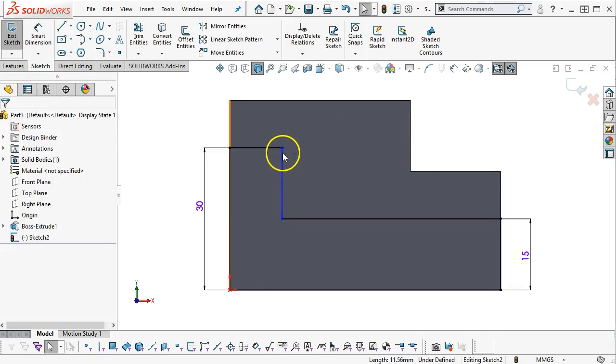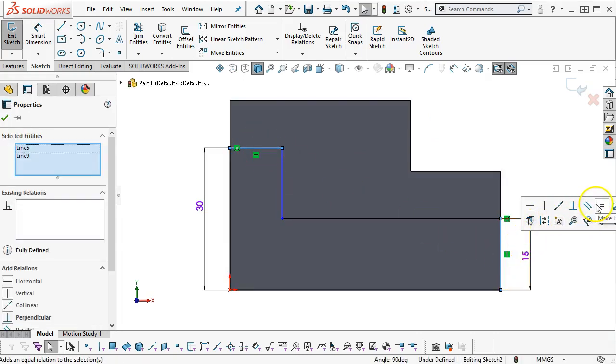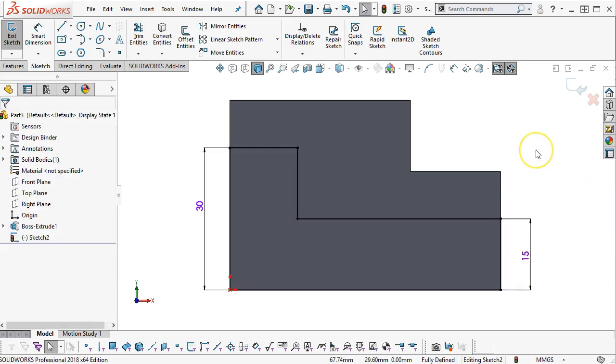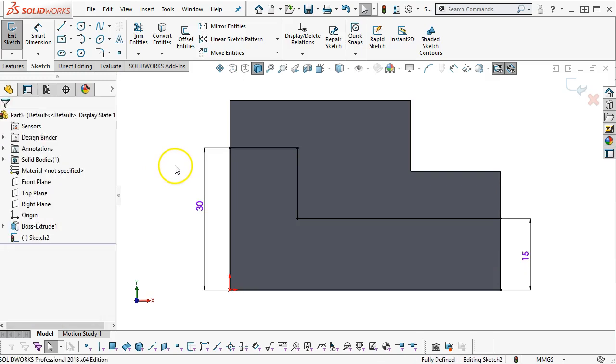All right, so our first relation then will be to set those two items to equal. If I find out it's not equal later on, that it was 10 millimeters, the thickness of the back, then I would come in, locate my equal length, delete that relation and apply the dimension or modify the geometry as needed for the correction.